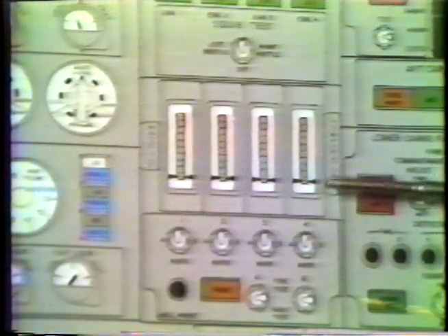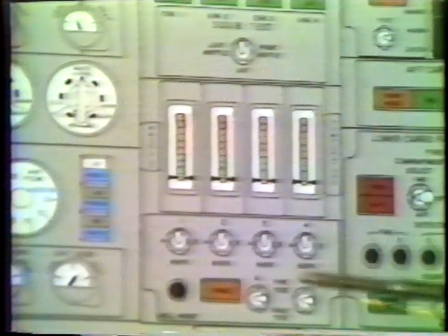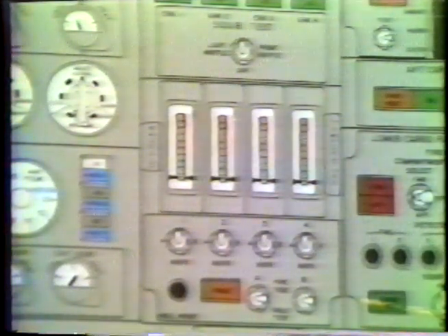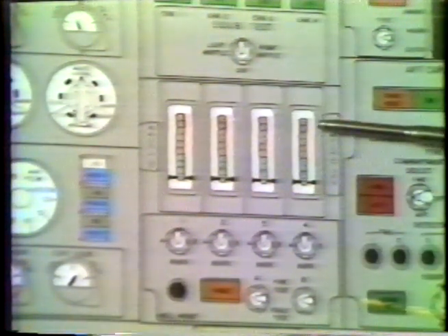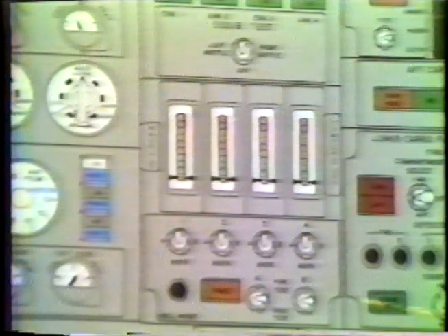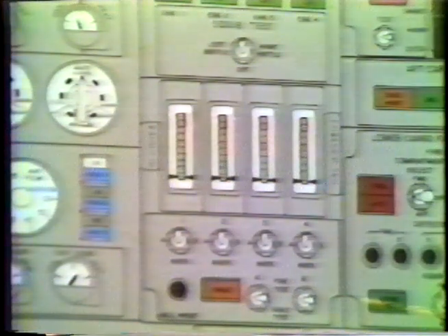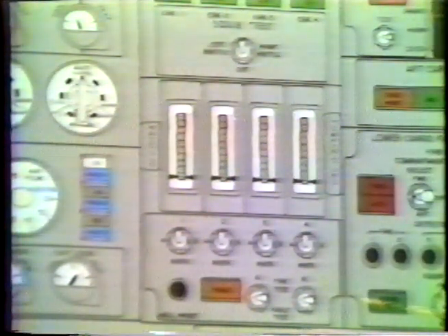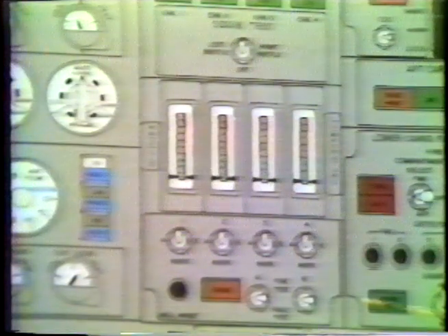If one sensor is failed and the other goes into the fire band, that will give you a fault, not a fire. When the switch is in both position, which is normal, it takes both pointers in the fire band to give you a fire warning. Now this was done intentionally to reduce the incidence of false fire warnings. On some earlier Boeing aircraft, the false fire warning was probably 9 out of 10 of the fire warning lights coming on, and after a while you got so you didn't believe it.